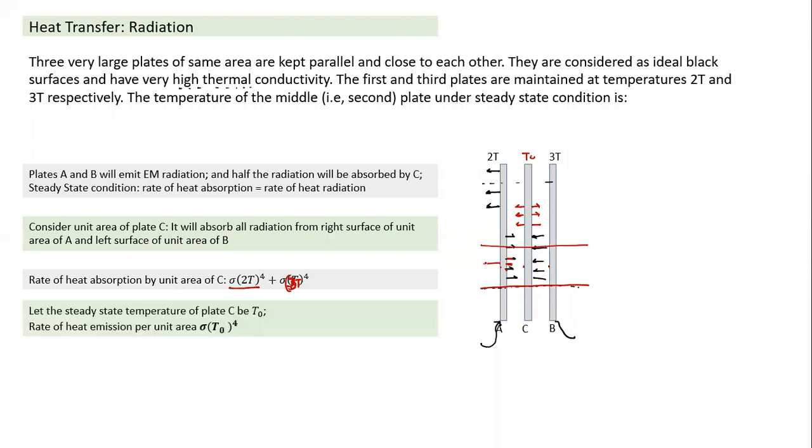And if its equilibrium temperature is T naught, what is the rate of heat radiation? I have written something, so all of you can notice what is missing here. Can someone notice, in the net heat radiation per unit area, is this term correct or is something missing? Anyone notice what is wrong here? I have taken what area? Surface 1 area. So there's something wrong. There's emission on both the sides, right, sir? Yes, emission is on both sides.